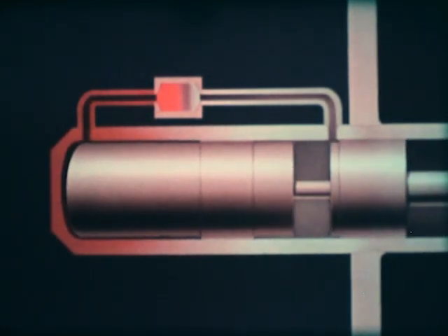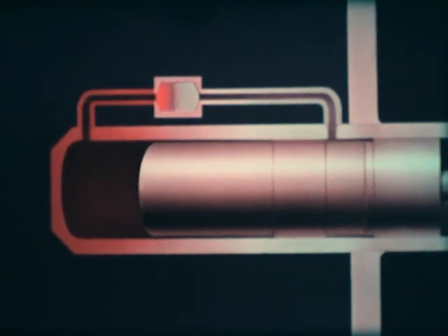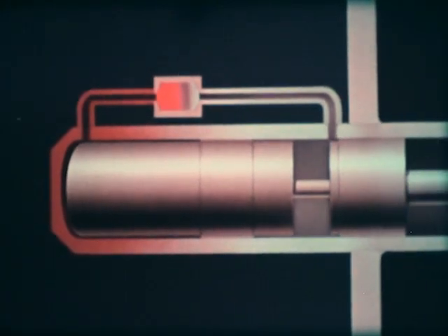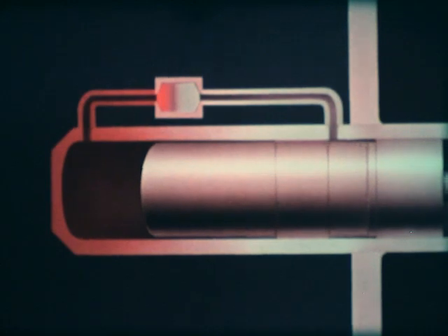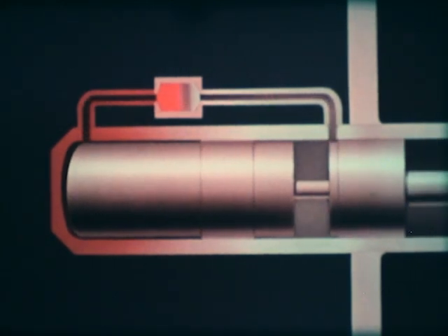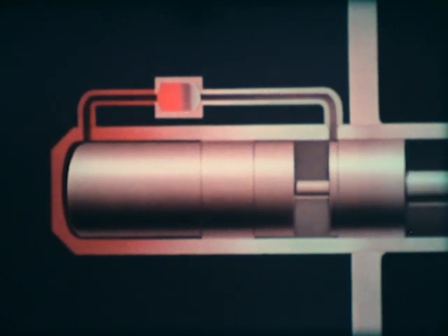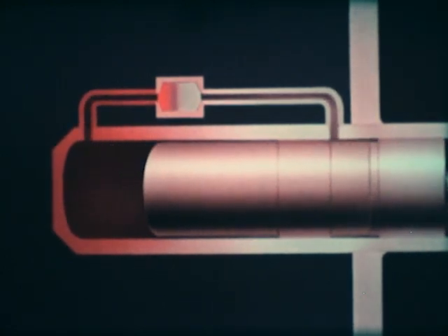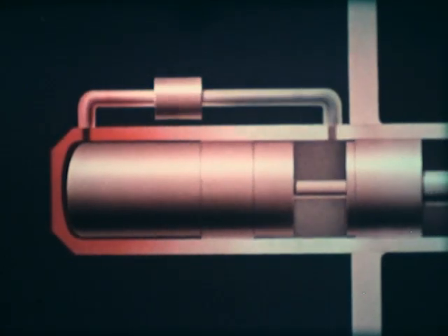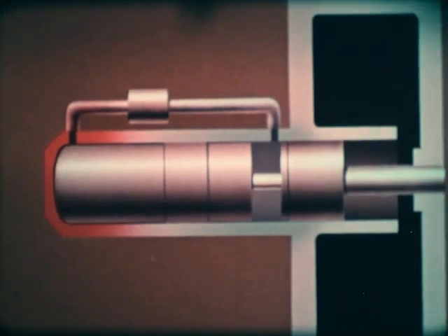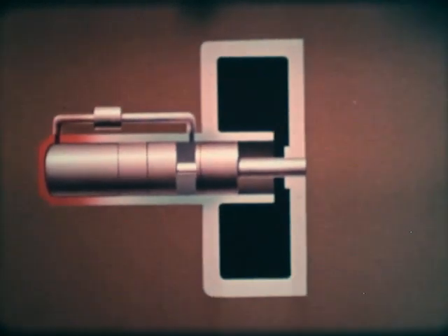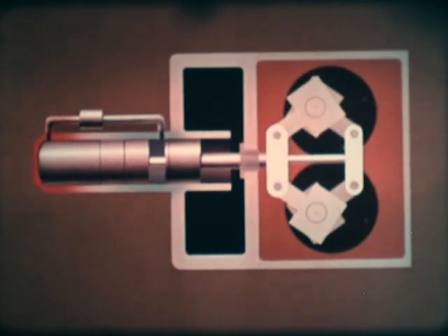The efficiency as well as the power is increased still further by raising the expansion temperature and by using hydrogen or helium as a working gas instead of air. The movement of the displacer piston is regulated by the power piston. A solution outstanding for its simplicity was evolved at Phillips. It is known as the rhombic drive.